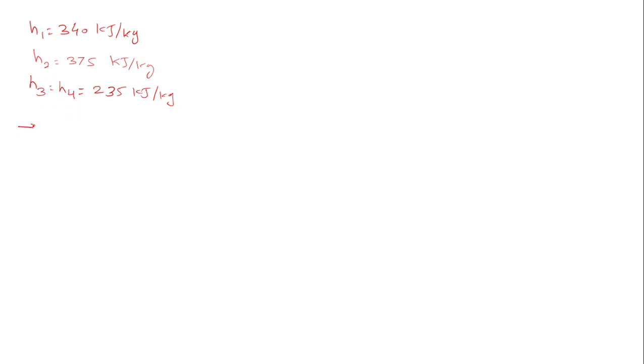We'll just go one by one. So first was the COP. Only when they are asking the COP, it is nothing but the theoretical COP, and the formula to get the theoretical COP is H1 minus H4 upon H2 minus H1. Okay. So put all the values of H1, H2, H3, H4. You will get the answer of COP as 3.69 around. Okay. You just note it. Just calculate that, because whatever answer I have got, I have just written, and these are again judgment values I have taken. I don't have the scale over here.